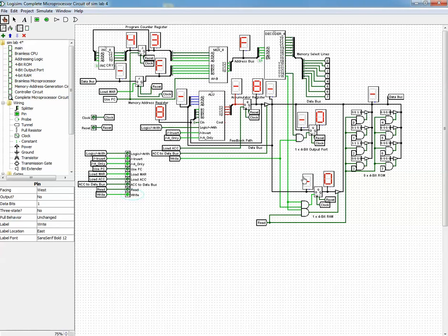Okay, so right now this has been enabled, and it can pass the data from the input to the output. But what data does it need to pass? I need to have this data, which is the 8, at the input to this register. So I need to activate this 3-state buffer. ACC to data bus needs to be activated, so I'll set it to 1. So right now I have this 1. I need right now to tick the clock. Once I tick the clock, I'm pretty sure that the input will move to the output.